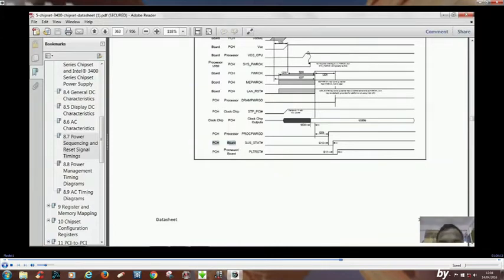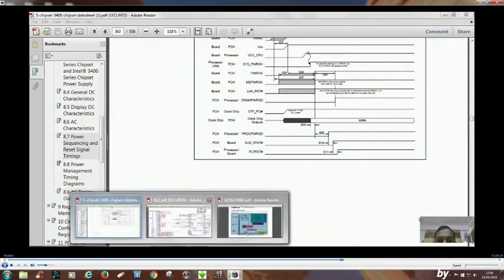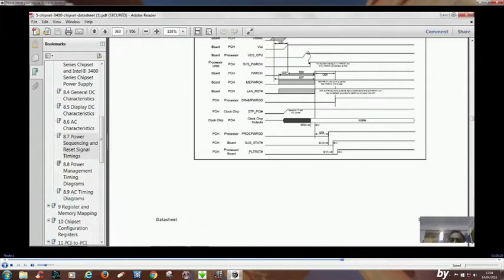And what is the next step? After the PCH provides power good to the processor, the PCH will generate SUS_STAT. And what do you mean by SUS_STAT? SUS_STAT means suspend status. Now the board is entering from a low power state to fully turned on, so SUS_STAT will be given a high value.